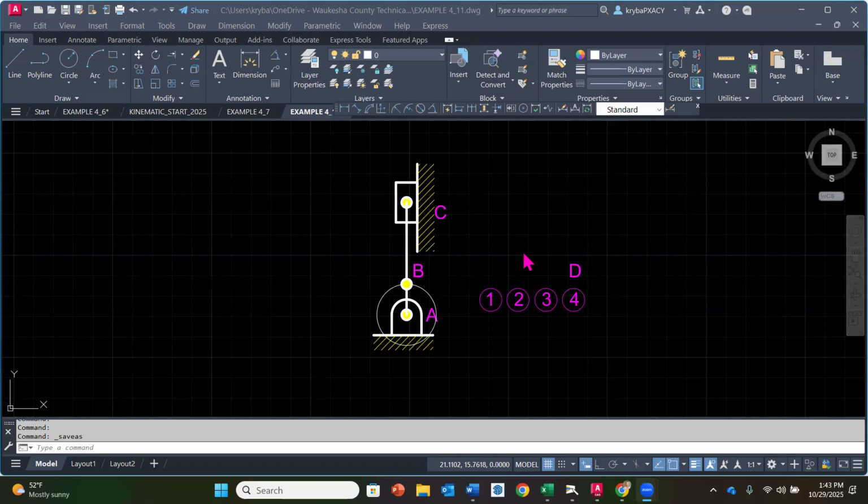So when we do displacement diagrams, the first thing we want to do is determine what the extreme positions are. One of them in this case is when we are stretched all the way up, in its highest position, and we know that to be the case here. If you don't have that information, you need to find that first. For early examples, we usually are given a random place in the cycle. If you know that's not one of the extreme positions, you need to find that first and then assign that as 0 degrees.